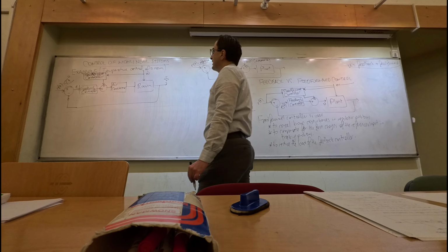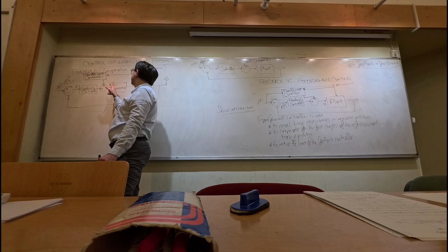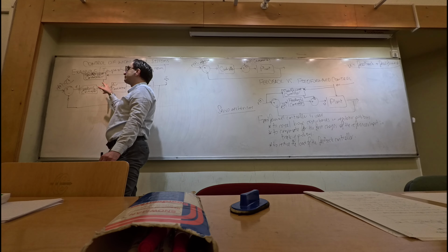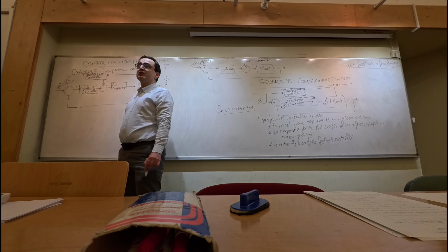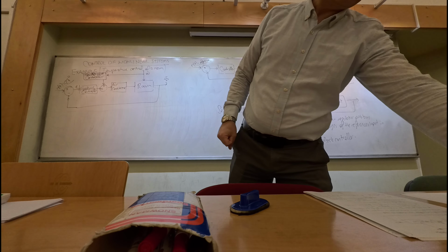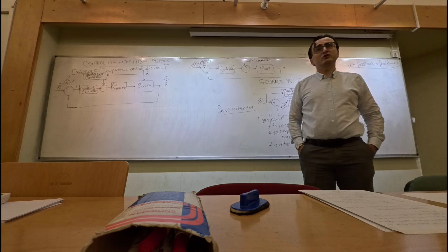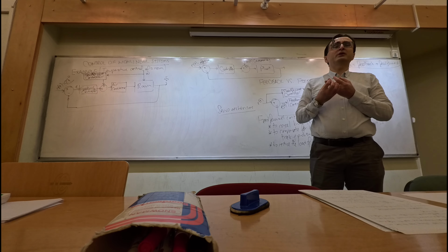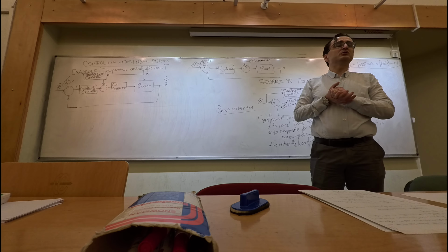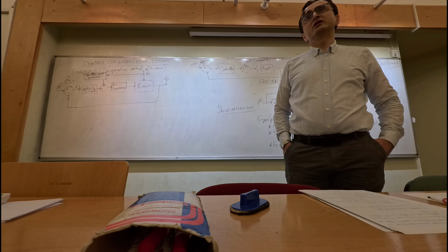That is going to be the task of a feed-forward controller. It's going to measure the disturbance, and it is going to try to compensate for the discrepancy before an error for the feedback controller to work actually appears. So this is just an example application. You can put some additional sensors outside the room, and then, based on the results of the measurements of those sensors, you can start your control action before an error actually starts to grow in the system.